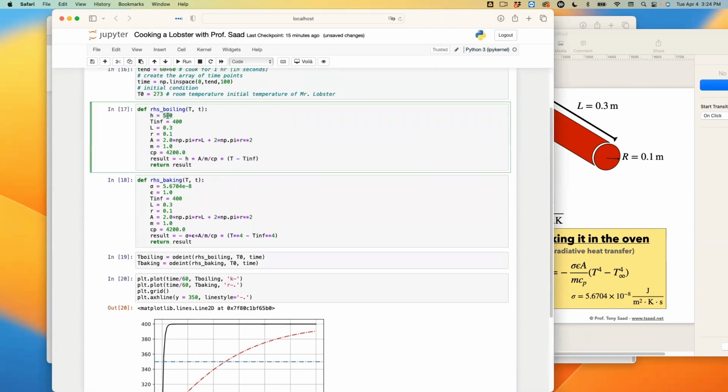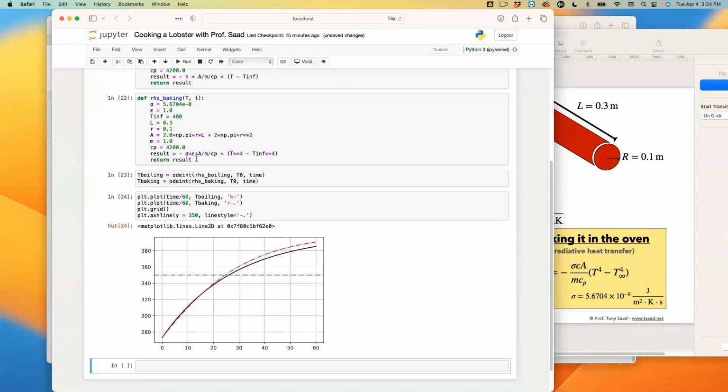Now, reasonably, those heat transfer coefficients are on the order maybe of 10 or 100. Then you can put this, look at that, for example. For these conditions, they're almost matching each other. So there's no practical difference, but the point is to illustrate the power of this method. We just solved two complex ODEs. The radiation one is a nonlinear one, and there's no easy solution for that.